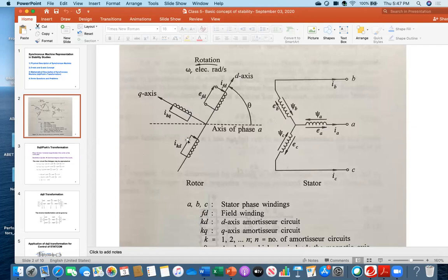But now come back to these three coils. I related all three coils. What happens once the voltage is built up in the stator circuit and current starts flowing towards the load or the grid side? Because of this current, another flux is created in each coil because of its respective current. Once current is developed, there is flux, and consequently flux linkage. But this flux always opposes the main field flux.